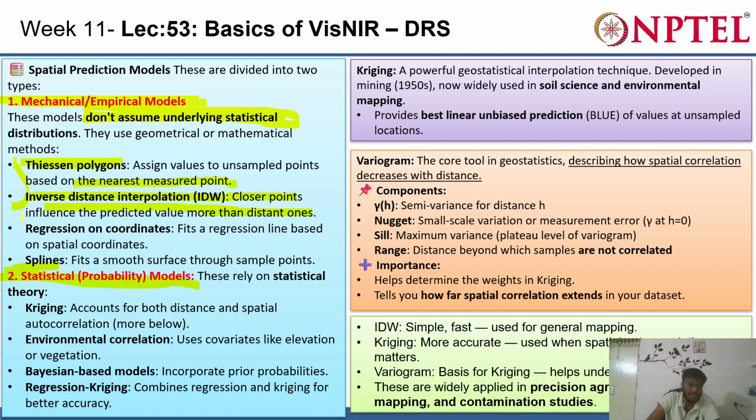So all these techniques have their own use. For example, for certain parameters like rainfall, we generally use Thiessen polygon or IDW methods, based on the accuracy that we want. If you want to consider a simple approach, then you can go with the Thiessen polygon approach. Then if you want to go into more detail, you go with the IDW approach. Okay, like that.